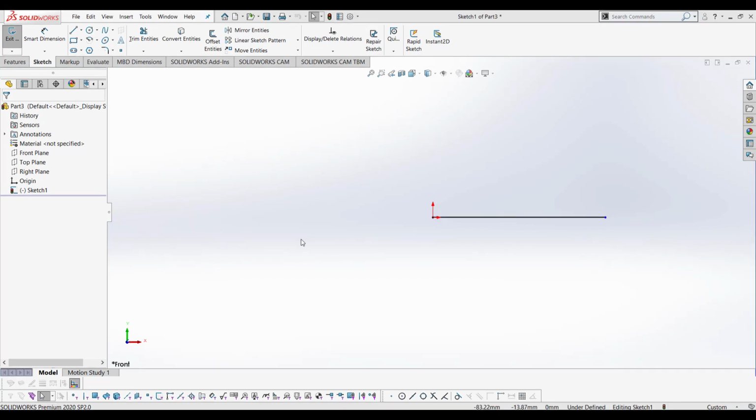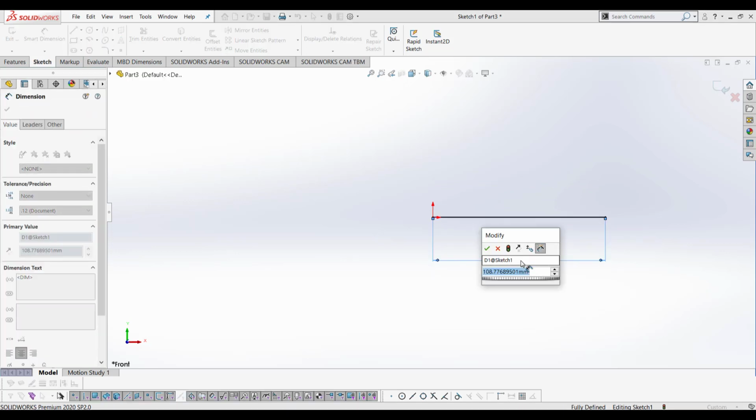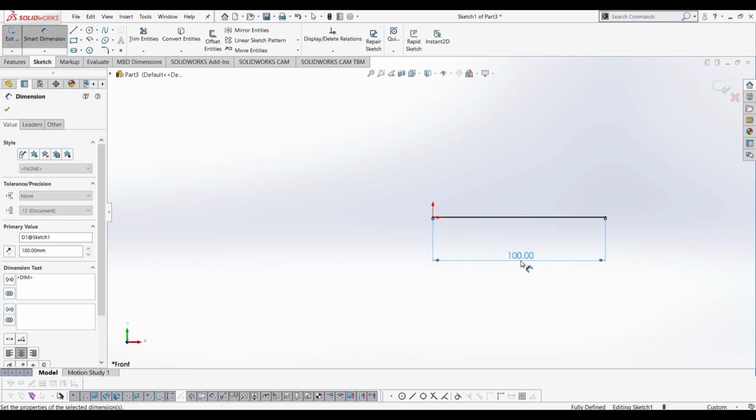The only component missing to have the sketch fully defined is a dimension, giving the line a length. To do this, we will be selecting Smart Dimension in the Sketch tab. Once selected, we will see that our mouse pointer has changed and shows a dimensioning sign. After this, we can go and select the line, pull upwards or downwards and click. This would open up the Modify tab. We are now able to modify the length of the line.